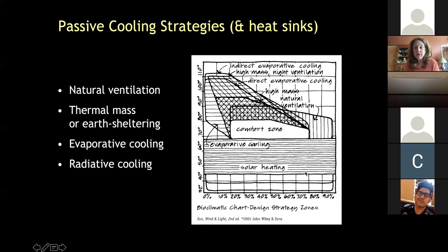And if you look on the right side, that's the humid area. And remember, the building bioclimatic chart is about showing what strategies are likely to be most effective in what kinds of climates. So what you're seeing here on the left side, the dry side, this is where you're seeing evaporative cooling and mass. It doesn't show earth sheltered, but that's part of the thermal mass, right?